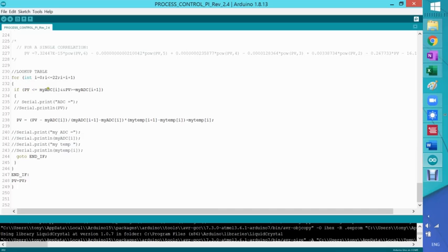Be careful there, because the way I set up the table is the way I got the data. The data was from the highest value to the lowest value. So when I'm testing where my PV, which is the analog value coming from the Arduino from 0 to 1023, fits, it is less than my highest value, but not less than the next value.